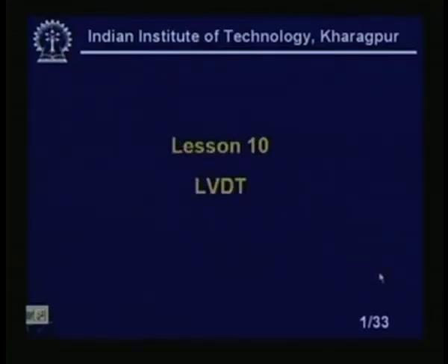Good morning. Welcome to lesson 10 of industrial instrumentation. In this lesson, we will study LVDT. The full form of LVDT is the linear variable differential transformer. It is basically an inductive or inductance based sensor, and primarily it is used for the measurement of displacement.